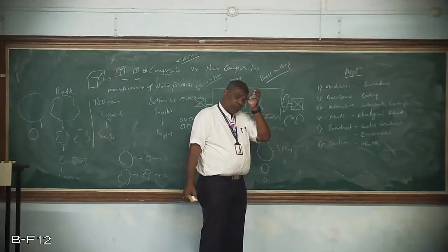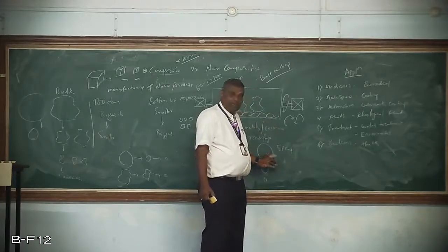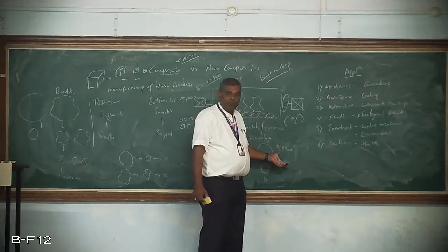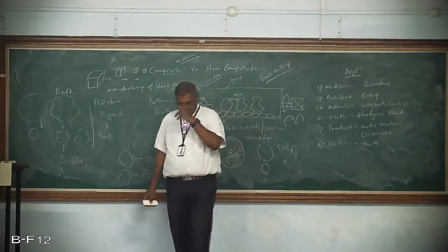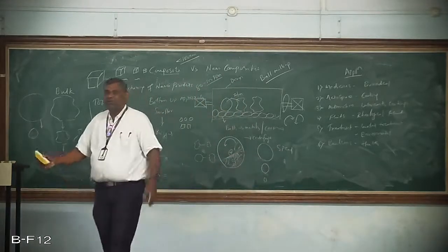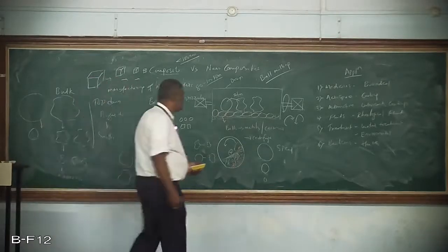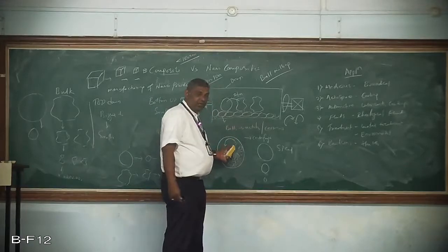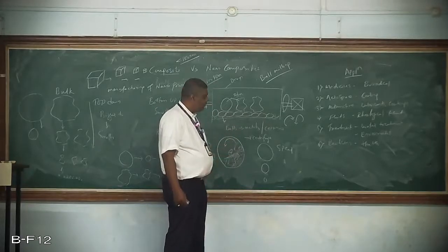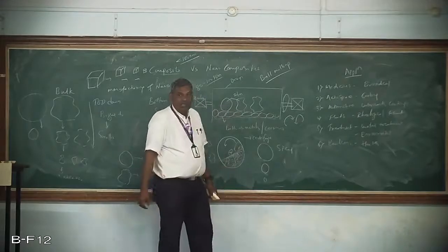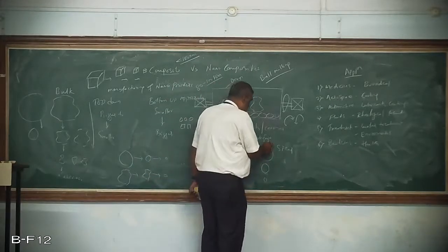If I use a low speed, then the impact will be more and the breaking will be more. As a result, the particle size homogeneity is not maintained. And what happens when this impacts with high speed and high velocity from the top? The raw material gets adhered on the surface of the balls.